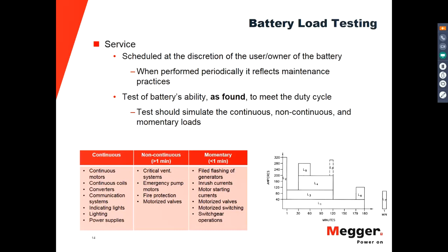So no previous maintenance, no previous preparation procedure. And the test has to be performed with the duty cycle, or the idea is to profile the load to mimic the actual duty cycle of the battery, or as close as possible.